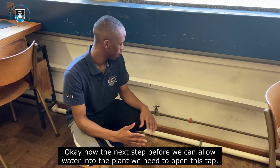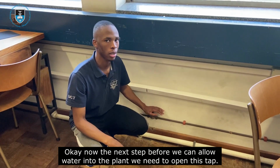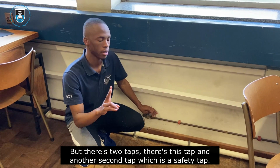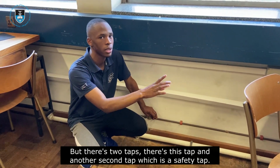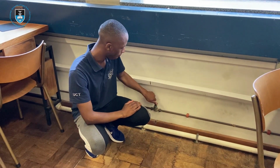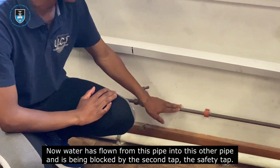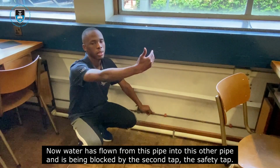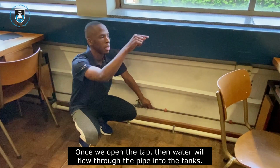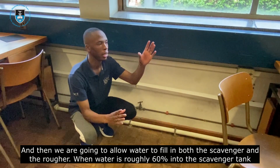Now the next step is, before we can allow water into the plant, we need to open this tap so that water can flow into the plant. But there are two taps: this tap and a second tap, which is a safety tap. So now I'm going to start opening the tap. Now water flows from this pipe into this other pipe, and it's being blocked by the second tap, the safety tap. Once you open that tap, water will flow through the pipe into the tanks, and we're going to allow water to fill both the scavenger and the rougher.